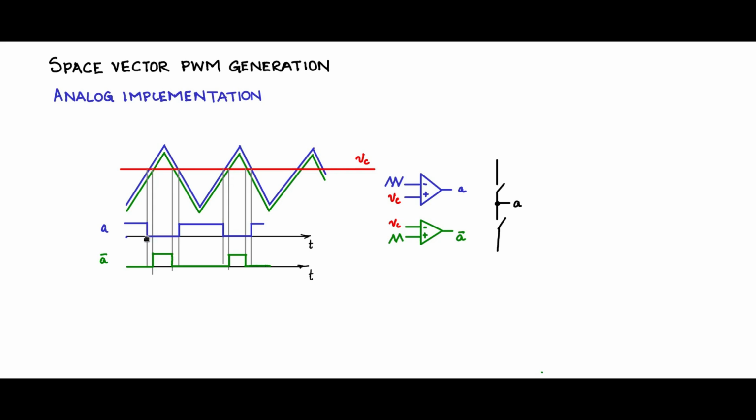Now you see the beautiful aspect of this is that during the transition, this is not a direct 180-degree inversion. As I was saying before, you have to give a dead time. When this is transiting down from on to off, and this is transiting from off to on, there is a period called the dead time. Likewise, when this is transiting from high to low and this is from low to high, there is a period where there is a dead time and both are off. This is called the dead time, so that the top and bottom switches are given enough time for changing state, because they have finite rise and fall times. They are practical switches. So this time interval is called the dead time.